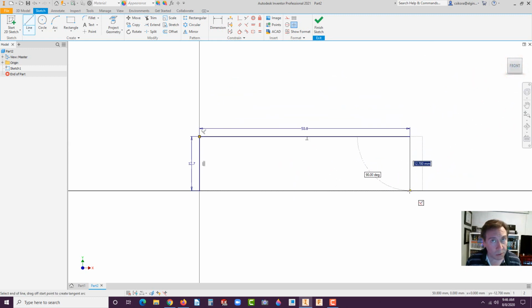And I'm going to give you some freedom to make your own bottle opener here. So click here, and maybe about 4 millimeters in, like so. Drag that in about maybe 8 to 9. Click. You can follow perpendicularity or an angle, or if you want, put a fillet in there, but we'll talk about that in a second.